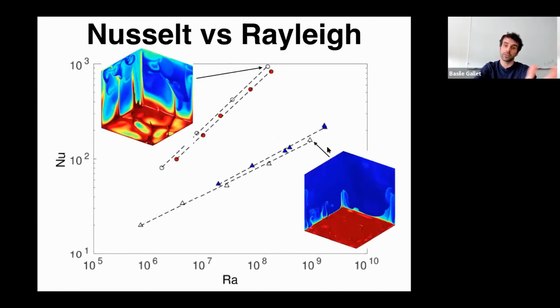Okay, if you look at a typical snapshot at a very qualitative level, you're looking at temperature here, and the temperature field for Rayleigh-Benard convection, the large values are really confined to the bottom boundary where you have to diffuse across the boundary layer, thus inducing large delta T's near the bottom. If you look at a snapshot in the ultimate regime, you get that the thickness of this large temperature region is typically the absorption length for the light, and then you have plumes that are wider and penetrate deeper inside the bulk of the flow.